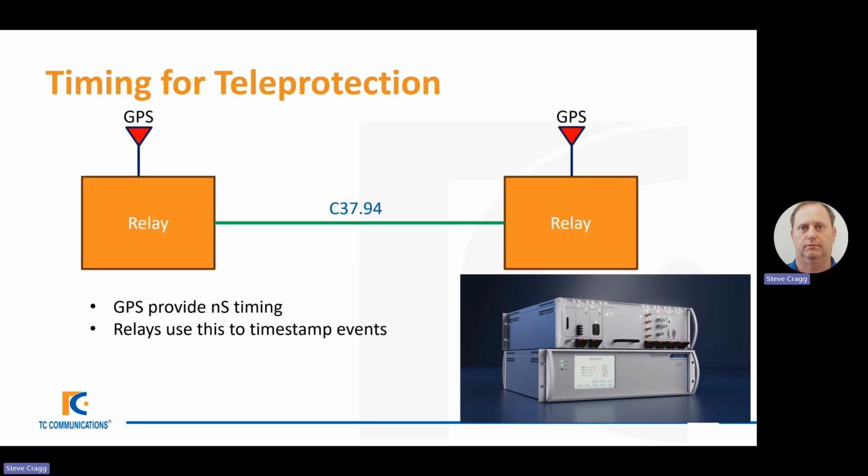And that's the problem for teleprotection, that if they don't have a means to synchronize their clocks, then eventually they will drift off of the accurate timing.